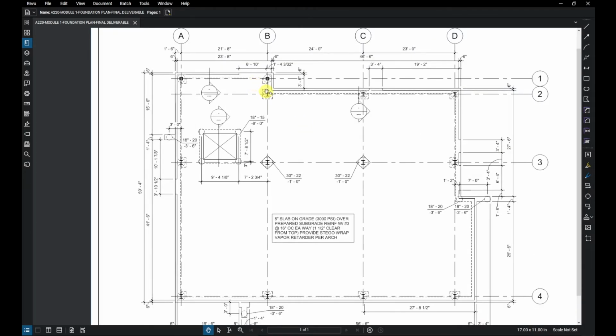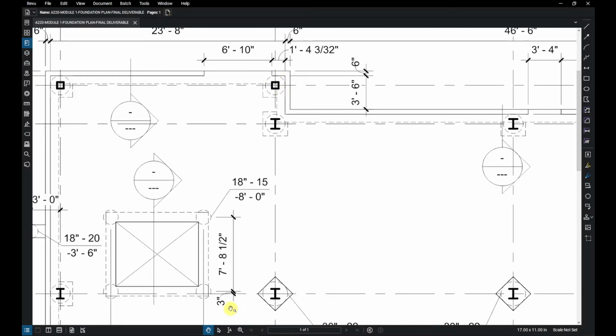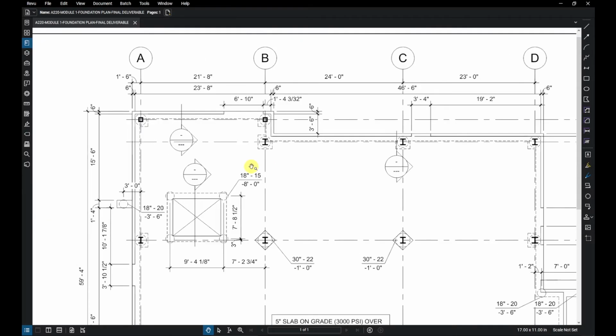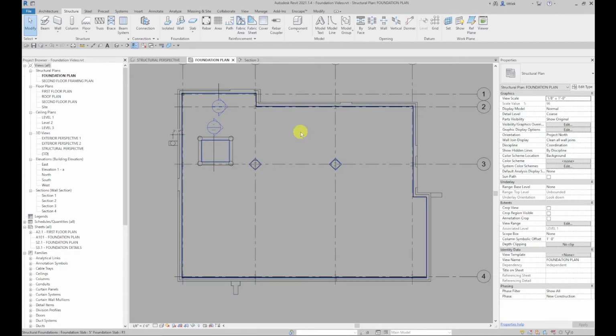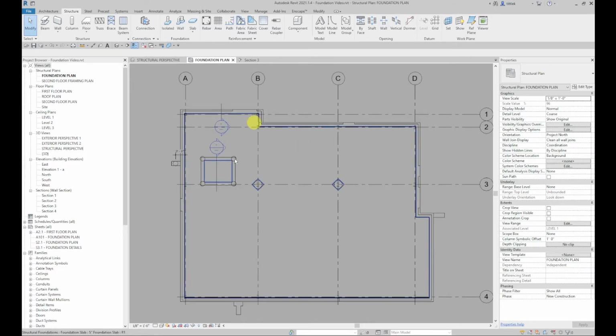Okay, so moving right along. The next thing that we are going to do is these exterior, or I should say perimeter column footings. Now these could be done a couple different ways. They could be done with an isolated footing and then another pier like we just did, so that they're 2 different things. I think if I were to actually do this building, I would probably do them that way because it would offer me some more flexibility. But for simplification of this particular assignment, we're actually going to use a pile cap.